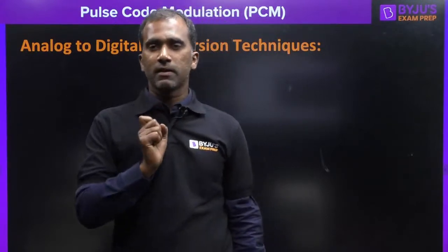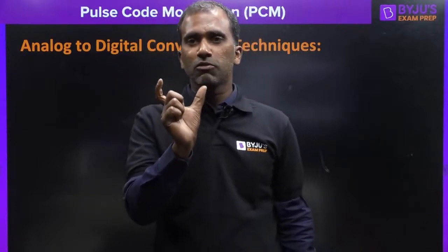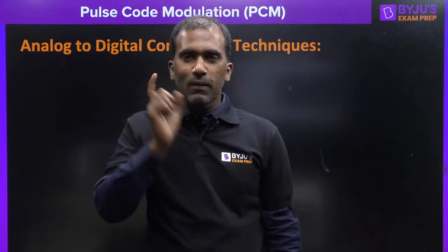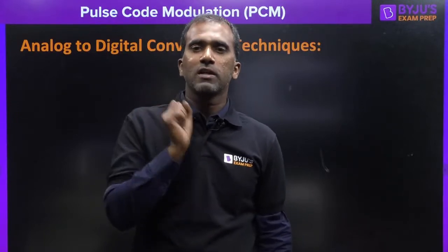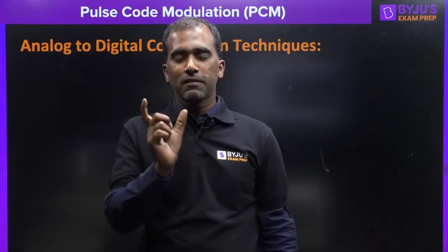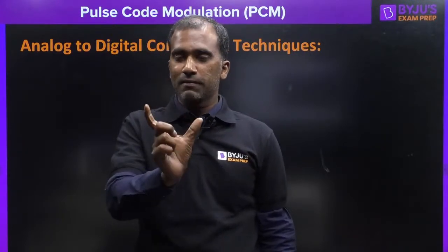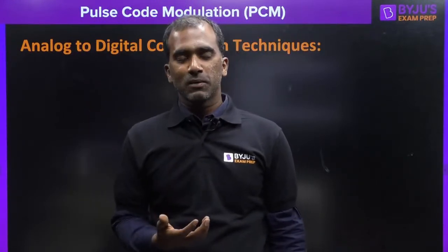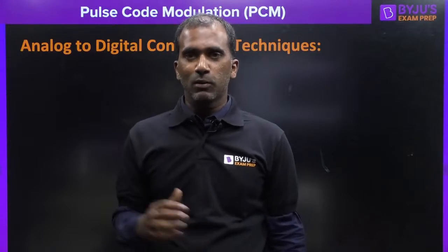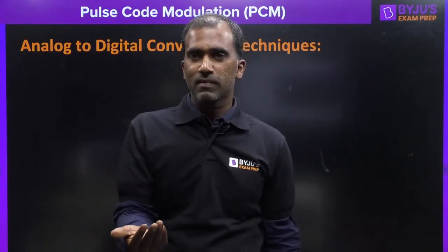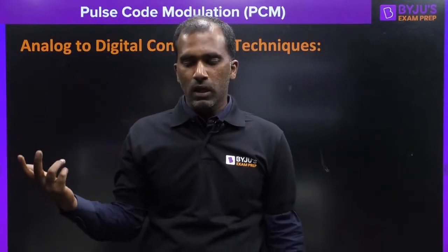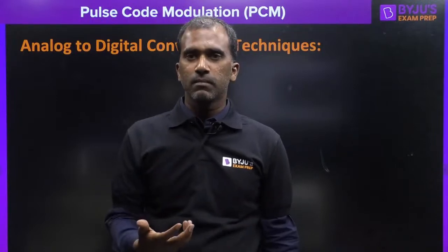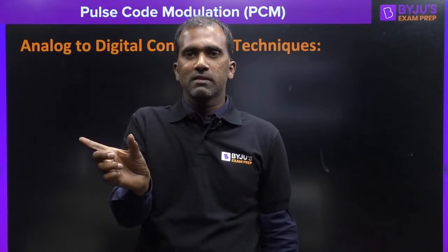Since we have a shortage of bandwidth, we can transmit only a certain bit rate wirelessly. I'm talking about bandwidth because, since bandwidth is scarce in wireless, we have a shortage of bit rate also. To get a higher bit rate, we don't have higher bandwidth, but we use other techniques, like the MIMO concept and a few other concepts, to increase bit rate, but not bandwidth. Whatever bandwidth is available, that is fixed.